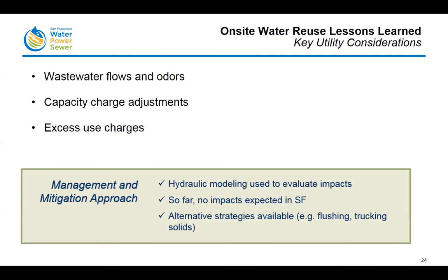How we have dealt with that here is that our utility has a water utility and wastewater utility, and we work with our wastewater department to conduct hydraulic modeling. The hydraulic modeling looks at whether there are actual impacts to wastewater flows and odors. We've run that on all of the projects that have come in for approval from the city. So far, we have seen no impacts that are expected in the city.